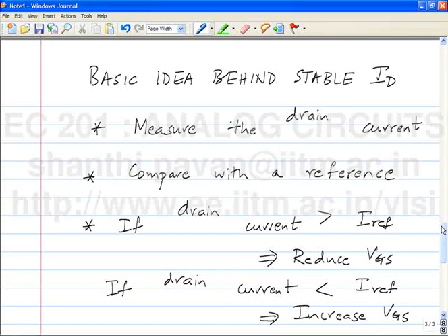So yesterday we had this thought experiment where we'd go to the lab, hook up the transistor, the drain connected to a sufficiently large potential to ensure that it is in saturation, and we put the ammeter between VDD and the drain. But I drain is the same as I source. So there is nothing preventing us from putting the ammeter in the source. So you can either measure current in the drain or current in the source.